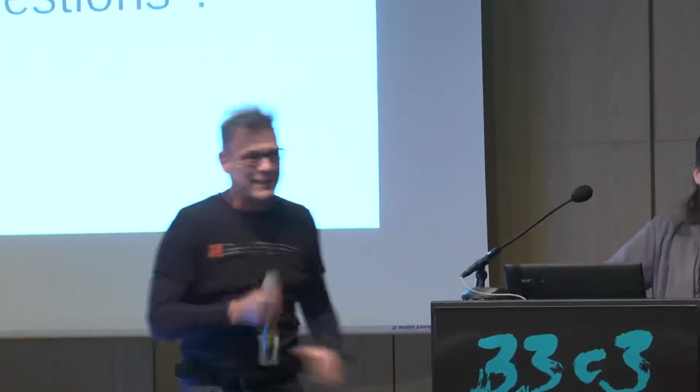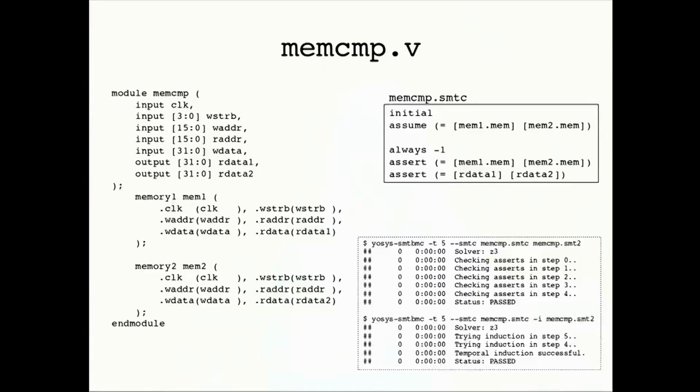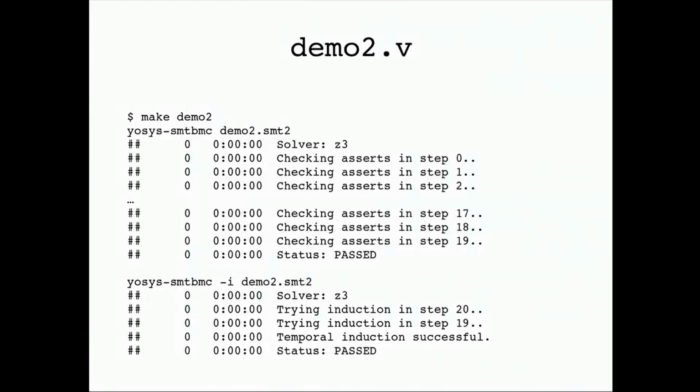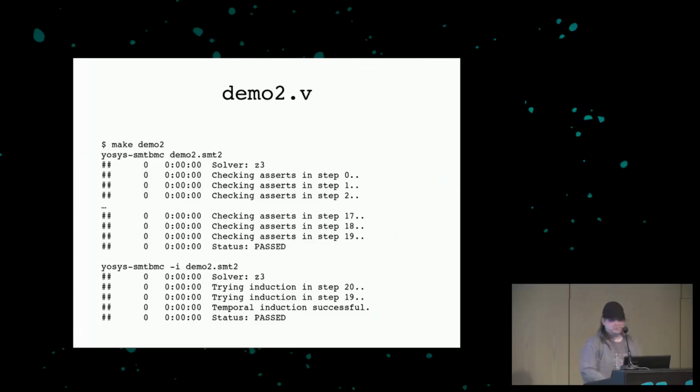This man, please. Yeah, I did not yet understand what is the difference between Yosys and just using any kind of Verilog simulator. I mean, the simulators also react on asserts and whatnot. Yeah, but you have to write a test bench that triggers the assertion. And with formal verification, you don't have to do that. You can just say, this is the set of valid inputs.